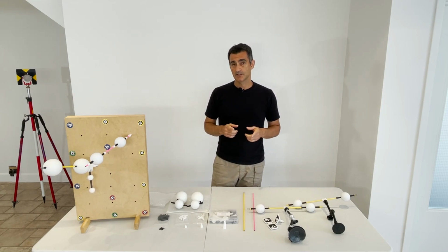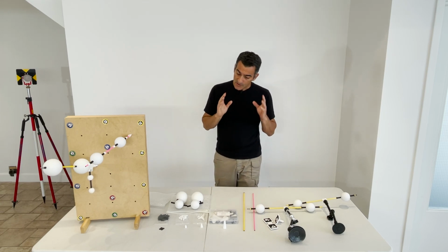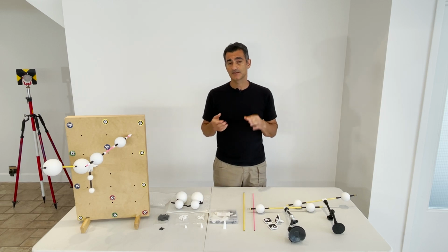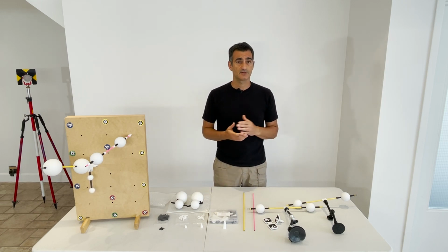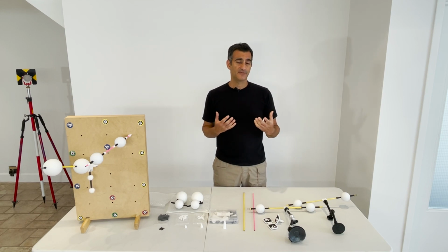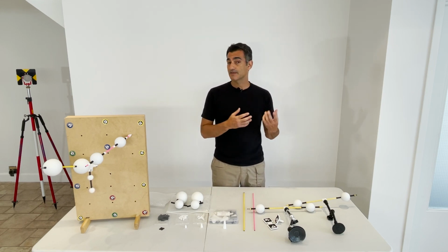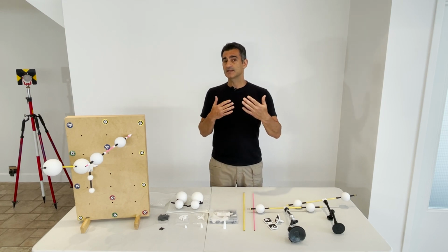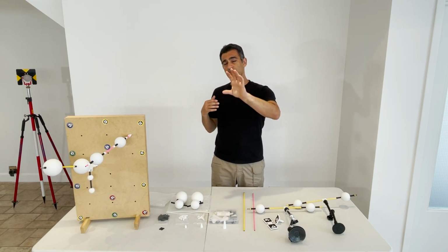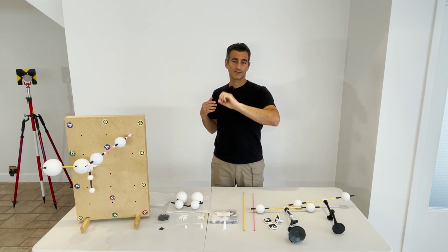So now let's talk about the laser scanner. The laser scanner has a different principle. It's not taking photographs per se to determine the 3D position of the rods. It's actually using a laser. So there are some side effects in using the laser, and there are some other things you have to think about. Just like in a camera in photogrammetry, if you move farther and farther away, you basically get less and less resolution.